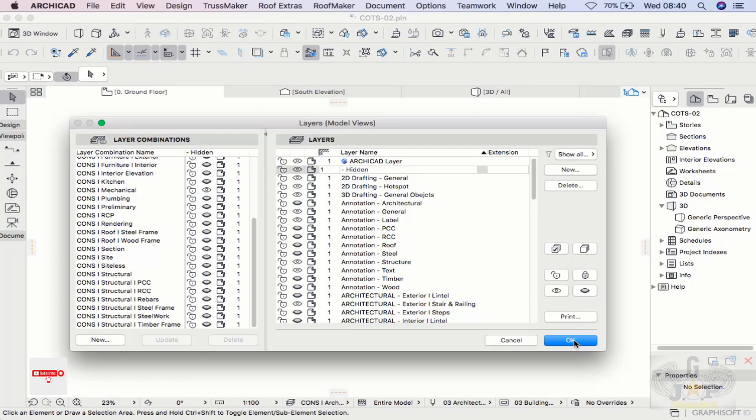And the good thing about ArchiCAD is that your windows and doors lay on your walls. So if you want to have a window aside, or a door, you can do it. You can delete your wall and keep your window there, but they are set on the wall. So your wall is like your layer combination, and your window or your door becomes your layer. That is the difference. The layer combination is the where, and the layers are the what. It's the same thing in Vectorworks: classes are the what, layers are the where. It's as simple as that.